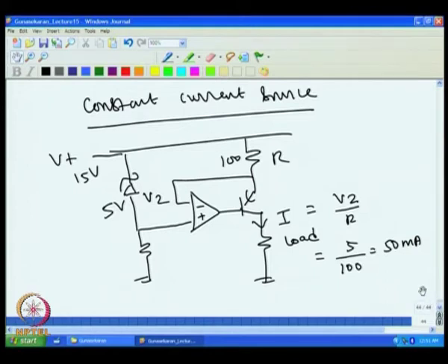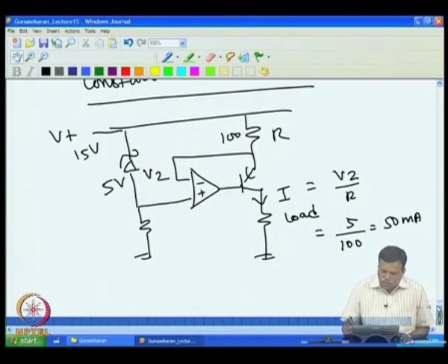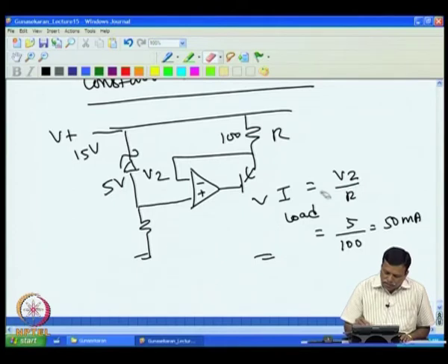Now, if I use this current source, I transmit this for long distance, and I want to convert this current into signal and the power, because the same current source should power the remote device, and also the current information is to be taken, and that should be used to control the valve, etc. So, normally what is done is, for example, I remove this load.